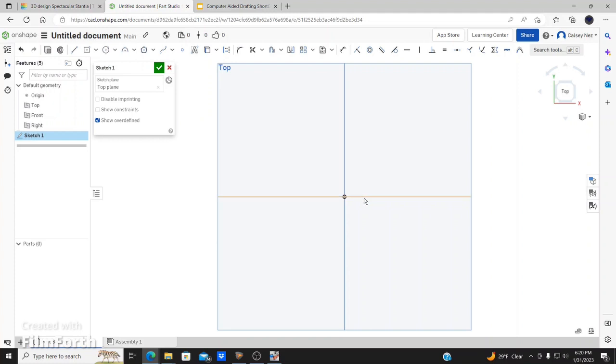Now, next one, circle. Plain and simple, it will be C, circle. Click the center, that's circle. All the other ones, bring this down. But on these ones, there's no key shortcuts. So the only one that has it is the circle. How about our arcs? 3-point arc, which is A, but the other ones, nothing.